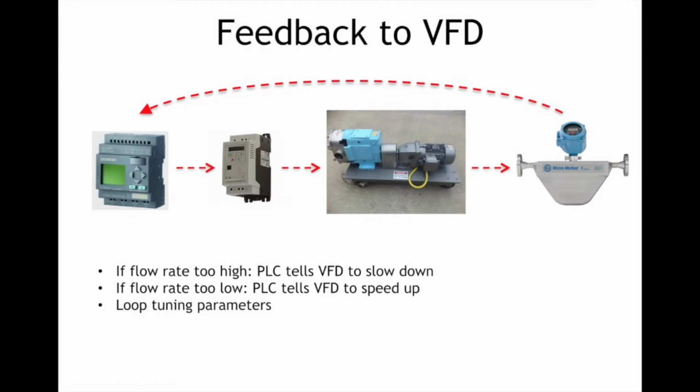And there are many different parameters that go into defining how this loop is tuned. If it's very far away, we could tell the VFD to react extremely fast. The risk there is that the flow rate will jump to the other side of the set point, and we end up just chasing our tail and swinging back and forth.